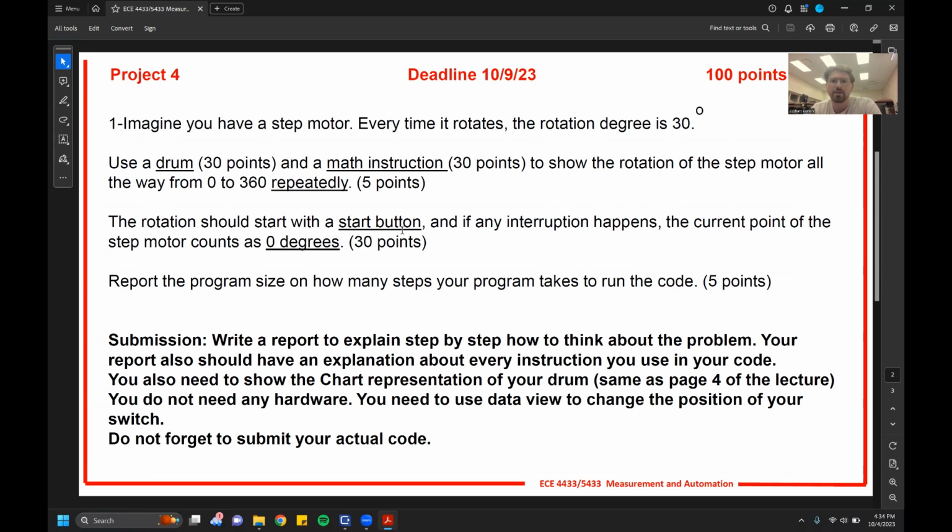It's fall 2023. This is Measurements and Automation, Project 4. For this project, we have to simulate a step motor. It rotates 30 degrees each time it's activated. We have to use a drum and math instruction to show the rotation of the step motor from 0 to 360. You'll see in my program when it gets to 360, it automatically resets to 0 because 0 and 360 coincide.